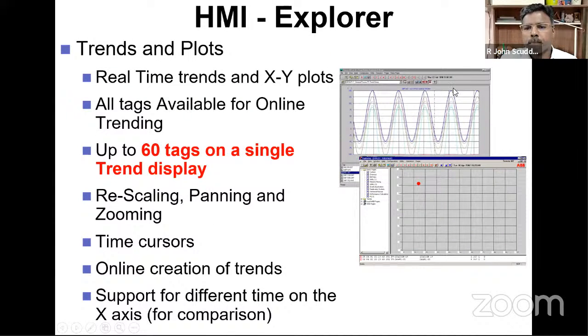And for every analog parameter, or even for a digital parameter, we are able to have trends. Trends are very, very useful. Imagine that when the main steam temperature goes more than 565, the turbine has to trip. Then the first thing the operation engineers will say is, oh, it was not at all high and it has tripped. So then, as C&I engineers, we will go and put up the trend and show, see, exactly at 565 only, your turbine has tripped.